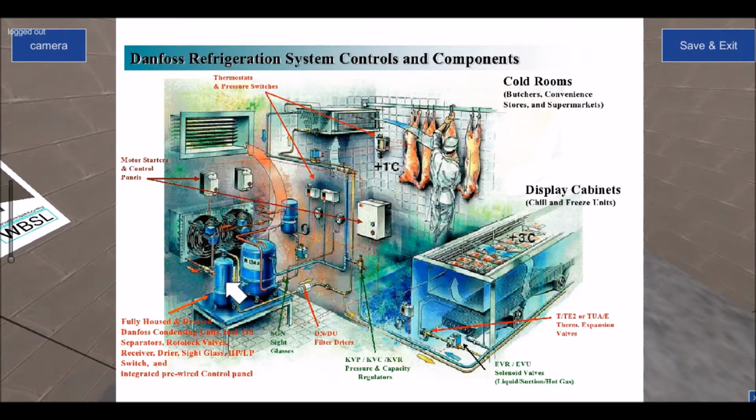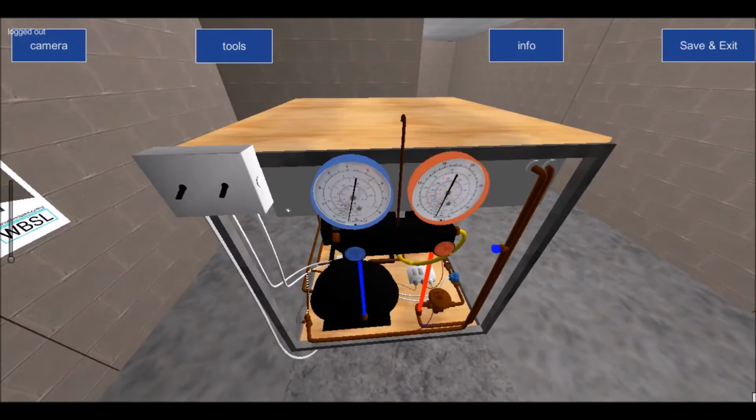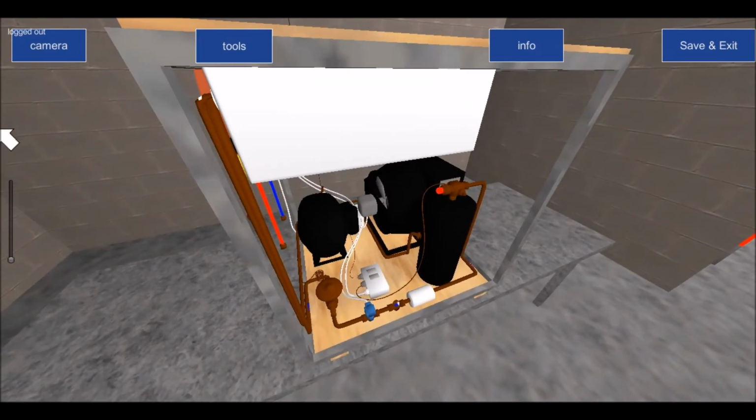So in the case of the picture that we have in front of us, this is a pump down. The control system is wired to create pump down every time the room reaches temperature. Equally, if I just click out of here, because there's a solenoid fitted to our own training rig, this is also a pump down system.